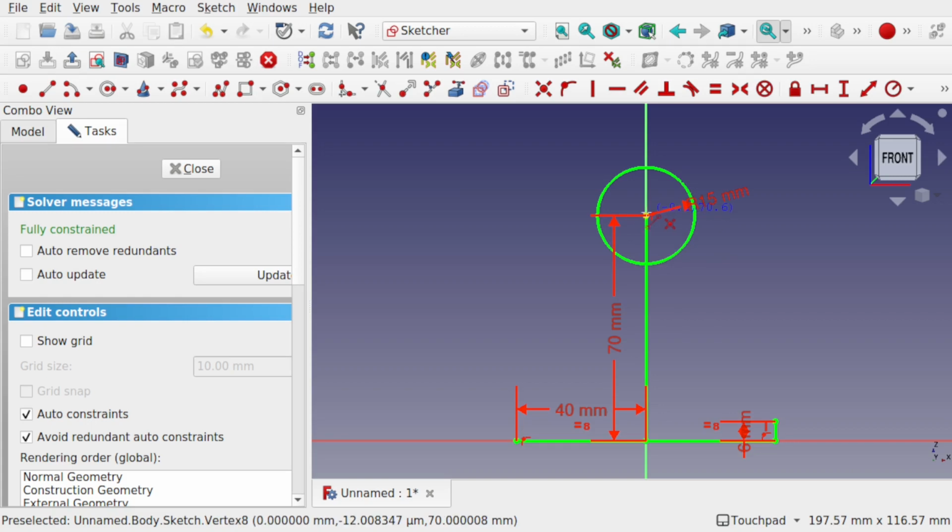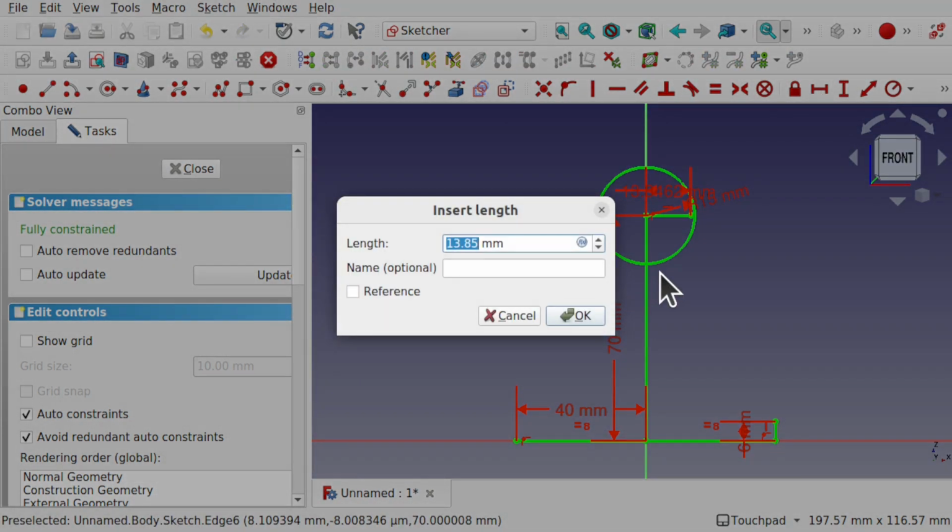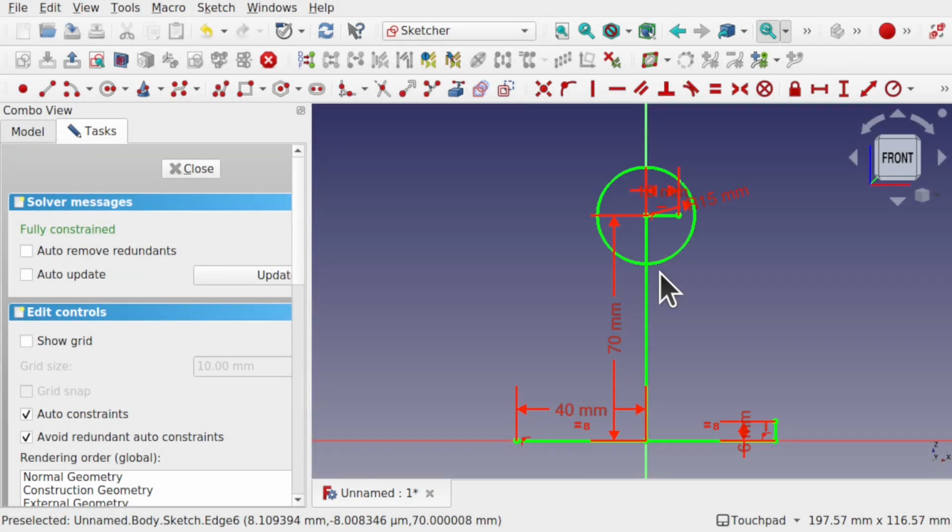So I'm going to have it stopping in the middle here, and I'm going to place a line, and this is going to be the size, well, the radius of this loft. So we're going to come out, let's come out this side so it's out of the way. And set a size in here, and this will be a length, and we're going to say this is around 10 millimeters. So we're going to loft into this point. So our top section, our top profile, will be of a radius of 10 millimeters.